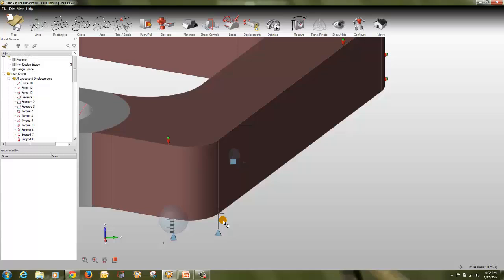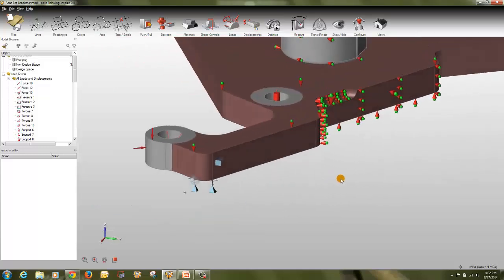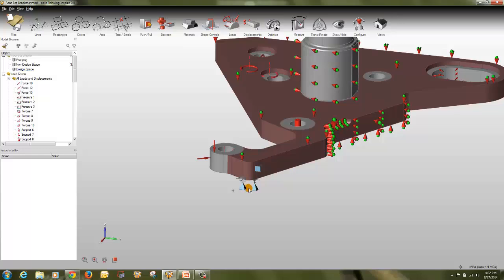They are represented by pyramids that appear orange when selected and blue otherwise. So in this way you can apply the displacement constraint. A displacement constraint is applied at a particular point on a model. You can choose to limit displacement in one direction or in all directions, as you can see here. So we have defined the displacement constraint in one direction or in all directions.